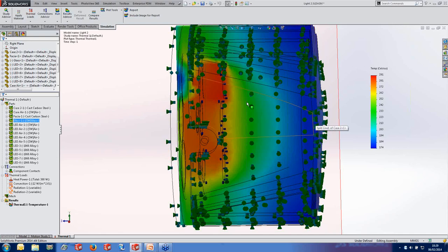But air being not a great conductor, it's not travelling. So potentially I need to do some design on the inside of the case to take heat from the back of the drivers straight through. So potentially, as well as a route for cabling in the back, which the sharp-eyed among you may have noticed there isn't any yet, I could have some metallic heat conductors coming through into, or much nearer the centre of the body and touching the drivers, to conduct heat straight to the back. Now if I could do that, potentially touch the back of the drivers as well, then it enables me to conduct heat much more effectively out of the back of the case.